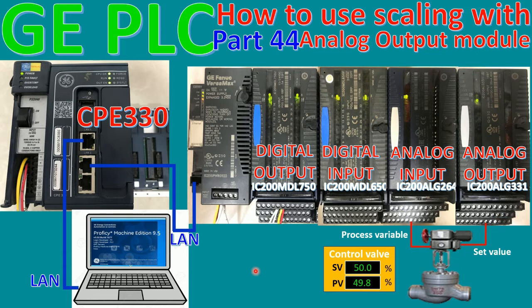Okay, and I will use Proficy Machine Edition and Proficy Workbench in this section to create the logic and the HMI and connect to the CPE 330. I already connected the LAN cable from my PC to port 1 of the CPE, and on LAN 2 I will connect the LAN cable to the remote I/O.